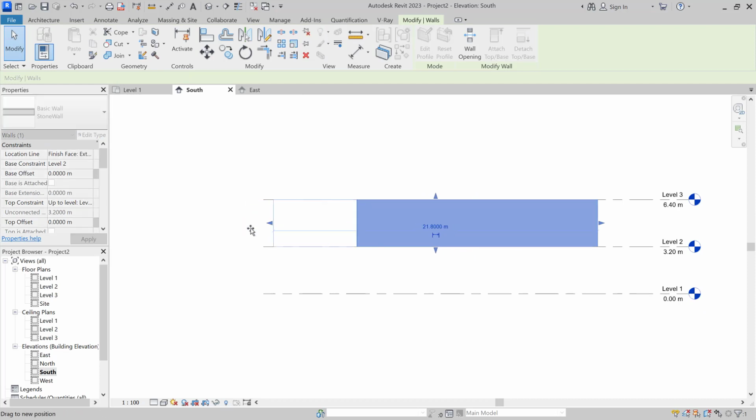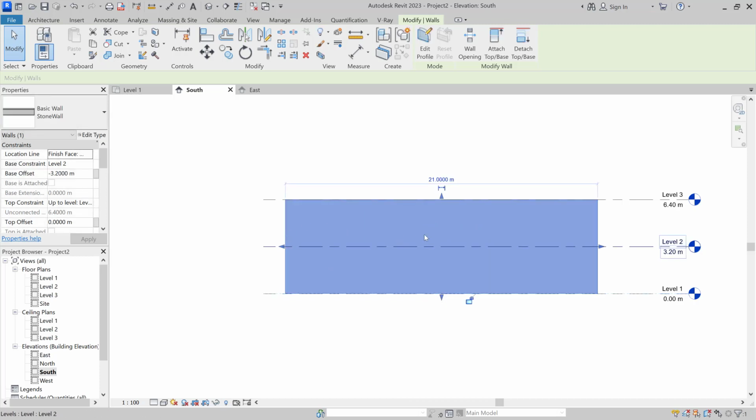You might have noticed that there are some errors here. You can easily just drag and drop them to whatever level you want. You can also change them. But when you change them this way, which I absolutely do not recommend unless it's to the sides, not in the levels, is because when you create this, there is a base offset here. There's a top offset as well. The top offset is 0. The only reason that you might want to have this offset is when you have a building which, for example, has a wall continuing 1.1 meters upward to work as a handle for the third floor.